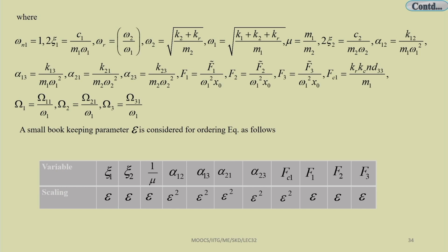So, you can note that the equations we have written are not unique. You can write the equation in a different form. Also, you can write the linear part using the matrix form, and then apply the modal analysis method to reduce this mass matrix and stiffness matrix to the uncoupled form, and then one can write down the equations separately.